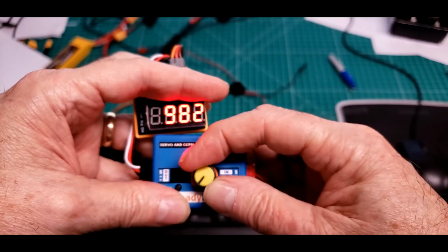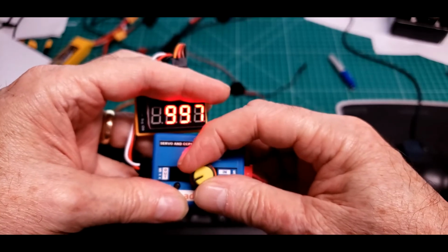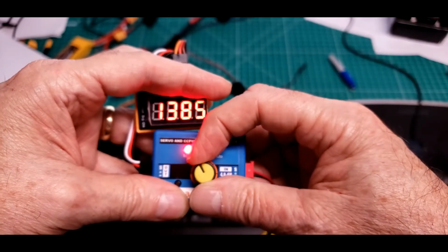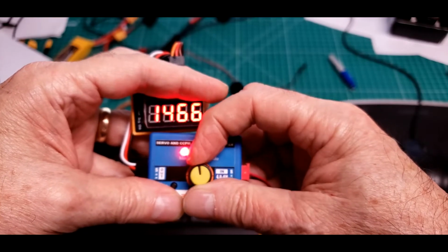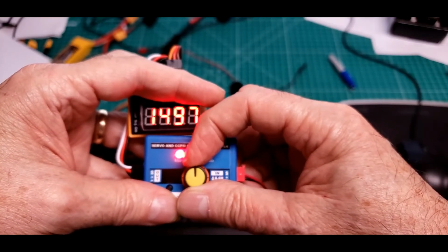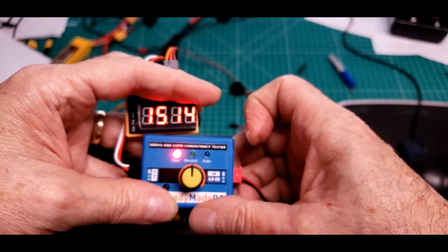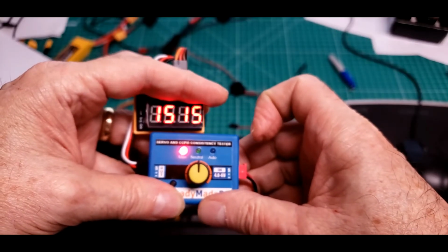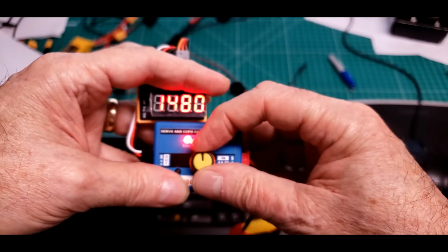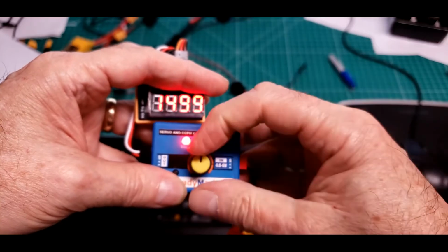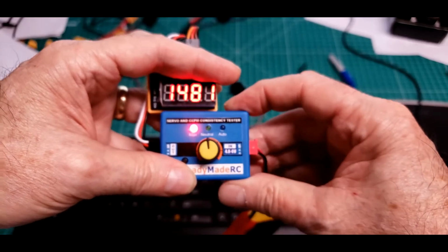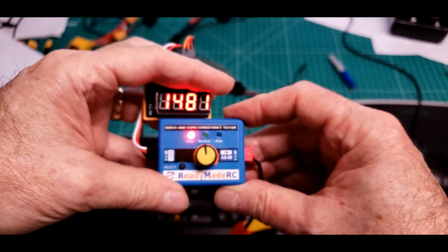Now as we turn this, the pulse width is going to increase. Well, it's increased to 1,000 now. Ooh, look, I'm coming up on halfway to what? Our normal old 1500, which I can't, neither one of these are precision devices, so I'm not going to be easily able to put it on 1500 exactly. Plus there's some capacitive reactance when you have something near a potentiometer. Anyway, 1500 for center, you see.